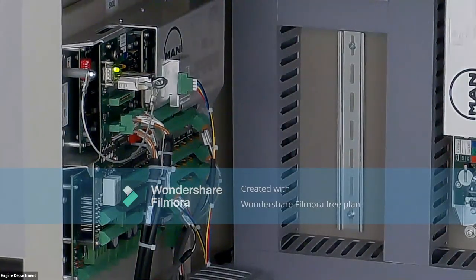For other engines, as I told you, it depends. The procedure before was to replace the MPC with a reconditioned one. Due to the frequent failure of the reconditioned MPC, nowadays MAN recommends replacing the MPC with a new one.